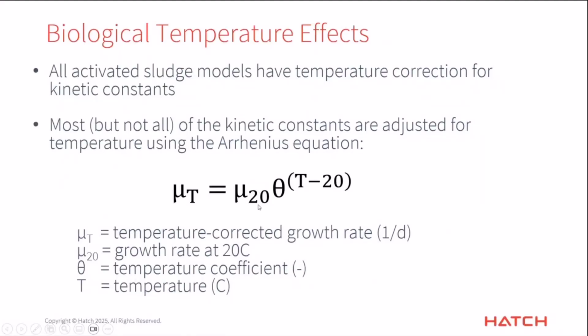So it seems that it's a very straightforward, sort of exponential relationship here, and it works really well. It's totally valid for, the experience that we have is we generally kind of say sort of like, 5, 8 degrees Celsius, something in that neighborhood, all the way up to 30. There's reasons why above 30, it might be a little bit over predicting the growth because at some point, the high temperatures become inhibitory unto themselves. And as we'll see later on, there's a double Arrhenius equation that we use in certain places. So anyway, but for like, let's say 10 to 30 degrees Celsius, this thing works great.